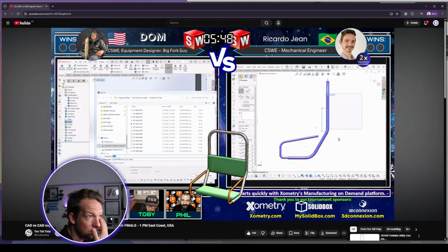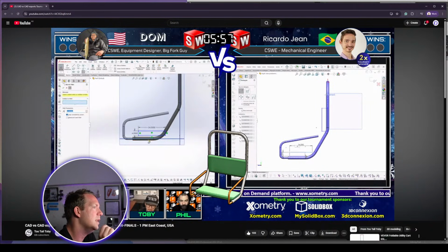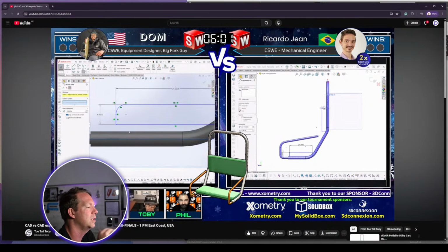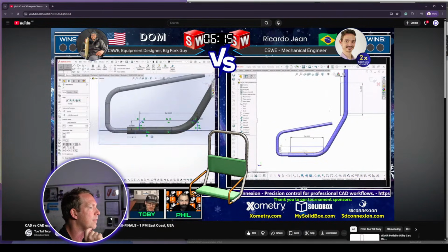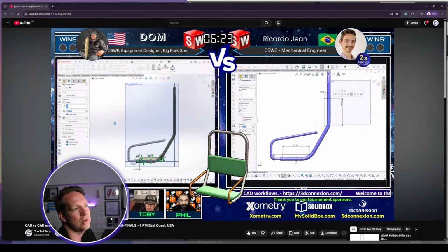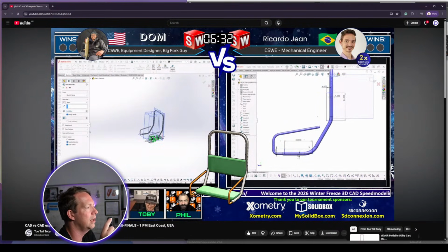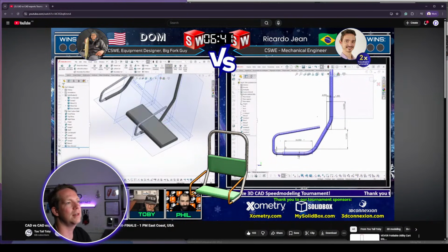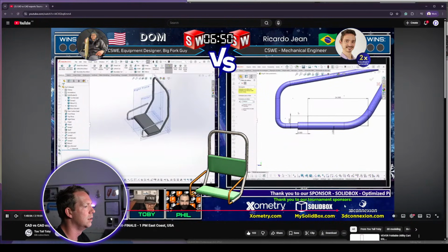If you can read the dimensions or remember the dimensions for how these bench seats are, though, it makes it very quick, because the bottom and the back of the bench seats are actually aligned with the center of the tubes. And if you can remember that, it saves you a bit of time. So it is important to dimension them, get them in the right spot, because if they're not in the right spot, then the cut or the indent that goes into those benches is going to mean that your mass properties are off, and it's going to be an incorrect value in the end.